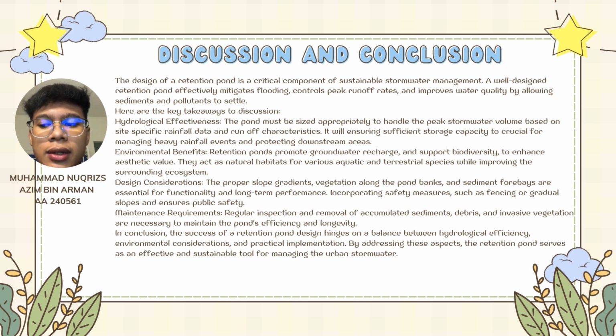Thirdly, design considerations. Proper slope gradients, vegetation along the pond banks and sediment forebays are essential for functionality and long-term performance. Incorporating safety measures such as fencing or gradual slopes ensures public safety.